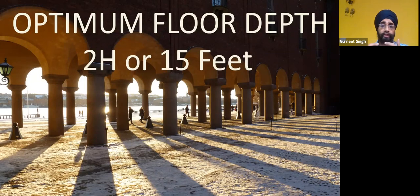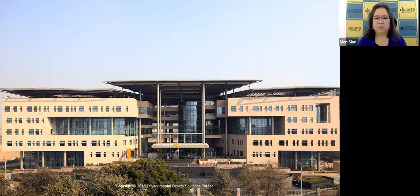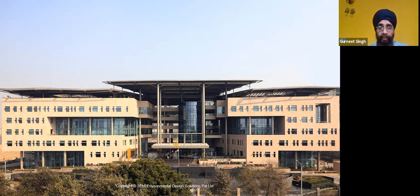So if your office space is too deep, then only certain part of the office will get daylighting. Rest will be partially daylit or maybe under lit, right? The same strategy was applied when we were designing the Punjab National Bank along with the architect Rajinder Kumar and the associate. So this was a competition project, and the client gave the brief that they want an energy efficient, sustainable building design.